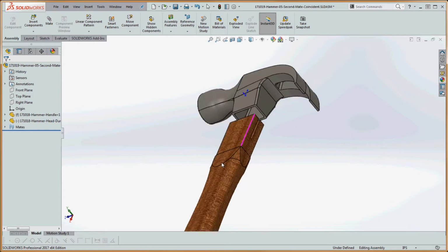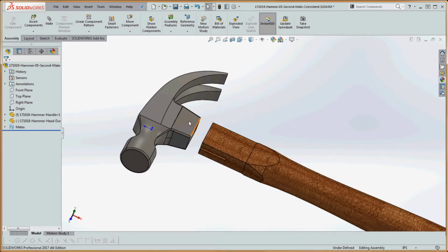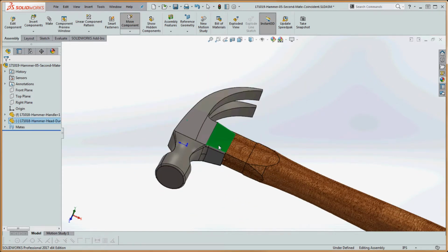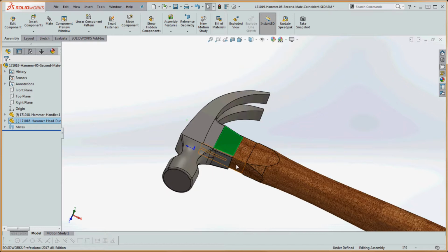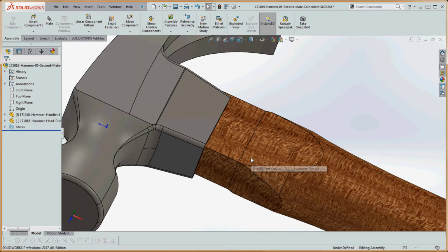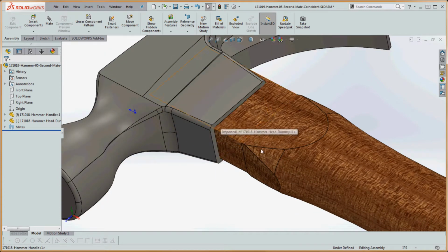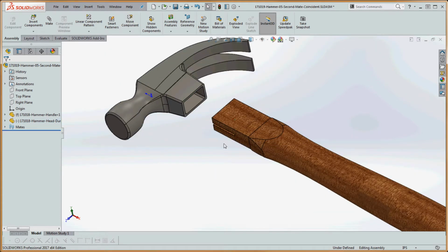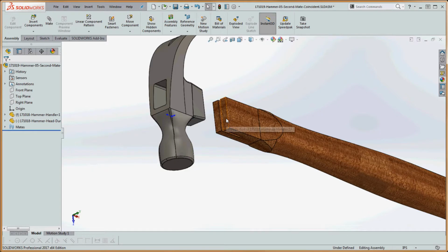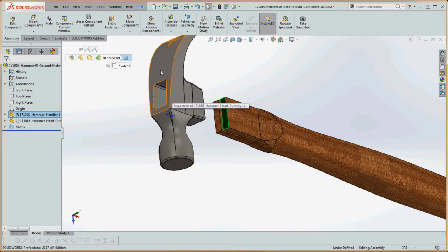Let's consider what we're going to be doing in order to get this fully defined. So as we pull this down, you can see that we could make some sort of relationship perhaps between this line and this surface over here, or if we pull this out a little bit, between maybe this surface and a line up here. This is not necessarily a flat surface. It's not going to be parallel to that surface down here. So we're going to have to be careful about that. But if we go between line and that surface, we could actually define it there too.